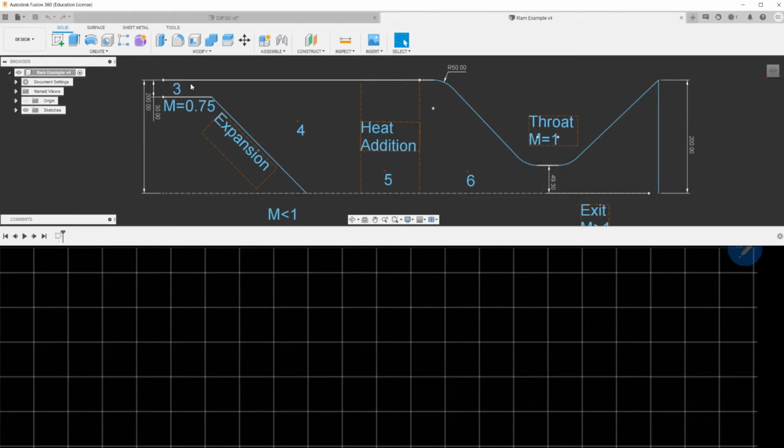If you decrease more than Mach 1, of course, you cannot obtain any solution because you will have no solution of the area-Mach number relation. Theoretically, by the area-Mach number relation, you can never obtain an area smaller than the throat area, which corresponds to Mach 1. So this is why, when you try to reduce more, you obtain not a number.